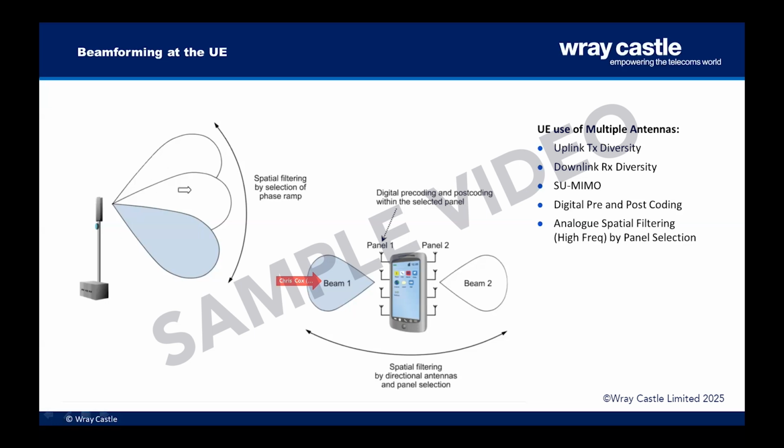The base station has to sweep through its analog controlled beams, and the mobile has to swap between its analog controlled beams until they hit upon the best combination. Needless to say, the control algorithms that are assumed within the specifications for 5G get a wee bit complicated, but this at least is the principle of the whole thing.